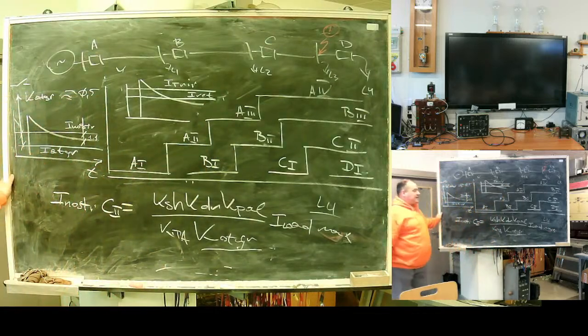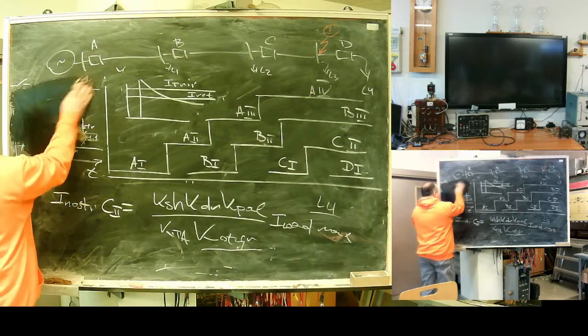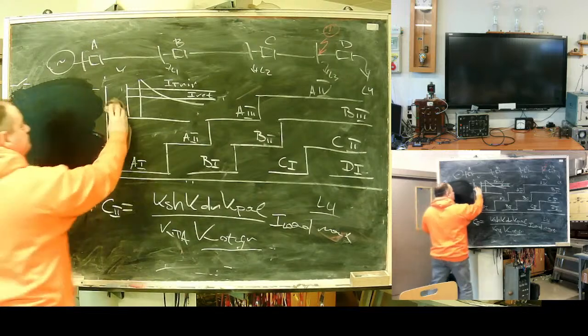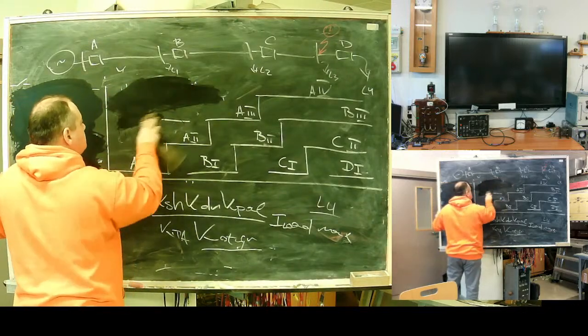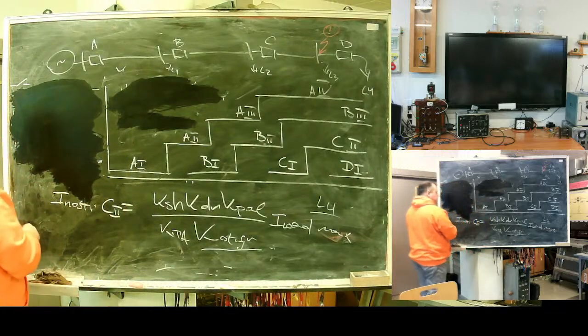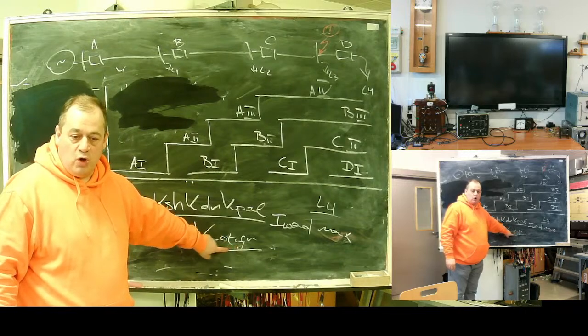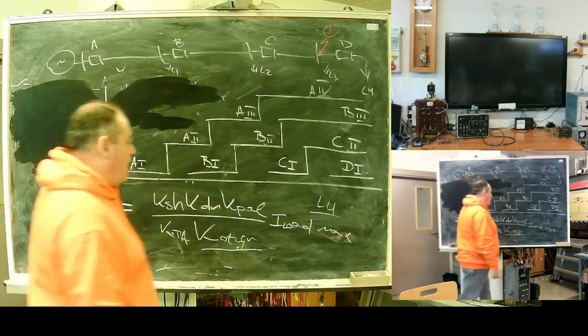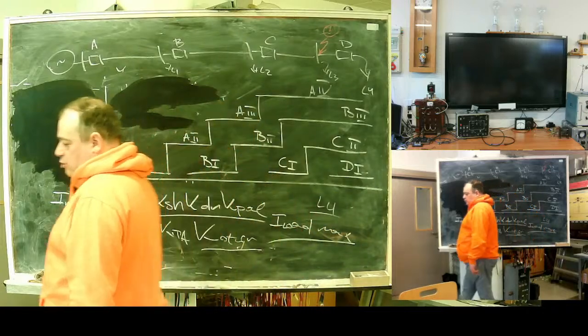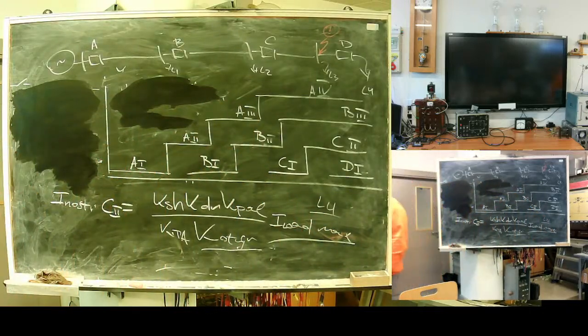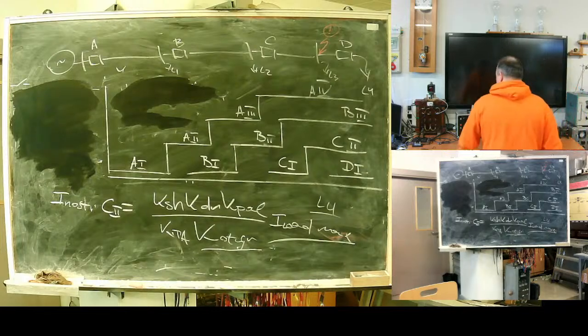I need to take into account this hysteresis ratio, or I fail. Return factor of your relay for non-instant zone and max load current. Here is the formula for the last zone, more sensitive.